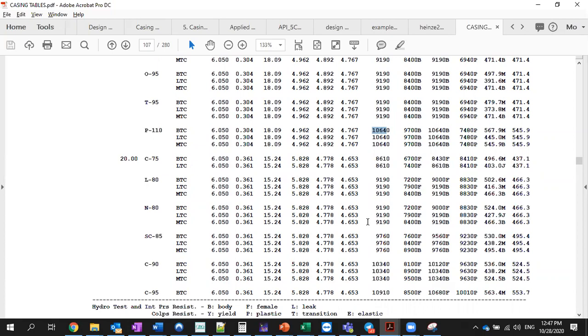So you start from the heaviest, you say, okay, I assume the whole wellbore is filled with that casing, right? It's basically the same weight casing all the way to the surface. And then you see, okay, this is not economical. I'm going to add another casing. I use 20, right? So 23 at the bottom, 20 at the top. Now, what depth should I set 20?